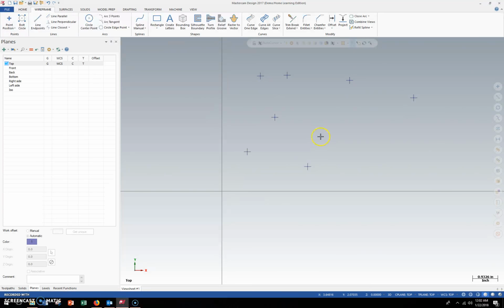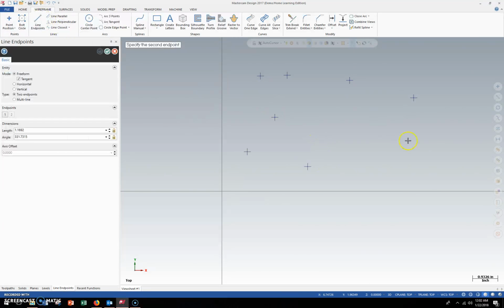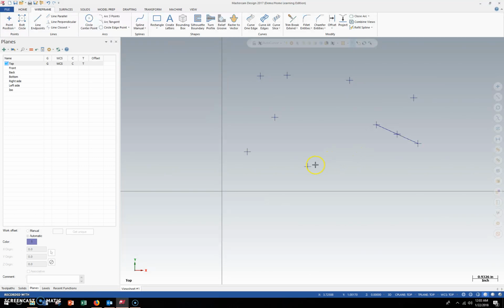If we had a reference point already existing, for example, though, that's one easy thing to do. If I wanted a point on an end line or a midpoint of a line, I could go ahead and use snap points to just drop these down. Usually that's how I draw. I will draw some reference geometry, like the outer shape of the part or something like that, and I will use that geometry to draw the rest. I'm going to go ahead and delete these for now.